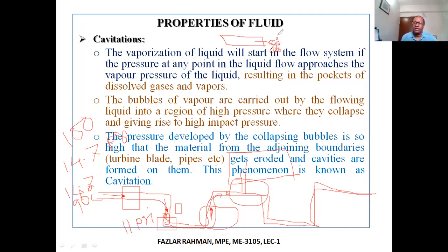And if you look carefully, say at a 10-year-old propeller blade, you will see there is a small hole, a pit, in the surface. So due to cavitation, the service life of a turbine blade or pump propeller is decreased, or sometimes the pipeline is also damaged. You are designing for 20 years, but your service life might be 15 years.